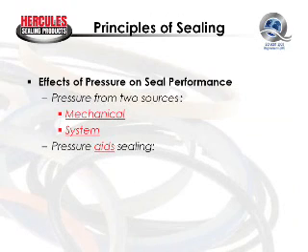System pressure helps improve the sealability, because as the force is transmitted through our incompressible hydraulic fluid against the seal, it forces the sealing lips even more tightly against the sealing surface. So therefore, we can say that pressure aids sealing. More pressure in the system, the tighter the conformity of the sealing lips to the sealing surface, and the better the sealability.